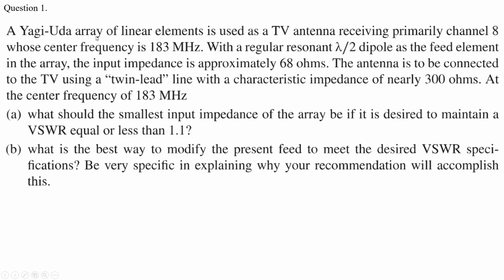So in this question, a Yagi-Uda antenna is being used for TV reception for channel number 8, whose center frequency is 183 MHz, and the driven element is a regular resonant lambda by 2 dipole whose input impedance is 68 ohms. The antenna is to be connected to the TV using a twin-lead, which means it is using a 2-wire cable, not a coaxial cable.